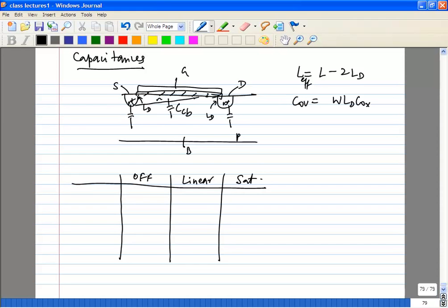Okay, and we are going to say CGC, gate to channel, is going to be Cox W L effective, and CCB is some value. I don't need to write it out, so it has some silicon over XD, the depletion region, W times L effective. The full expression for XD I'll give in the notes, you don't need to know it for now. So you have some CCB.